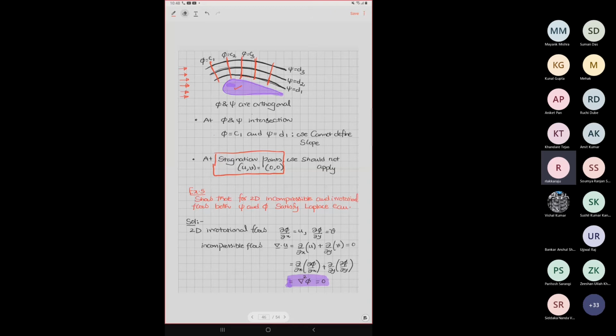And the stream function and velocity potentials are the natural coordinate system for solving CFD problems, which always align with the body, which we may never have thought about. But from math, it naturally comes out that the specialized coordinate system where computational programs work so efficiently is this stream function velocity potential coordinate system, because they are orthogonal to each other and they fit the body.